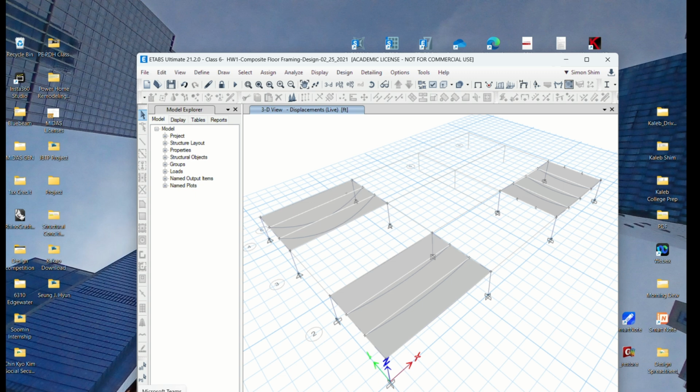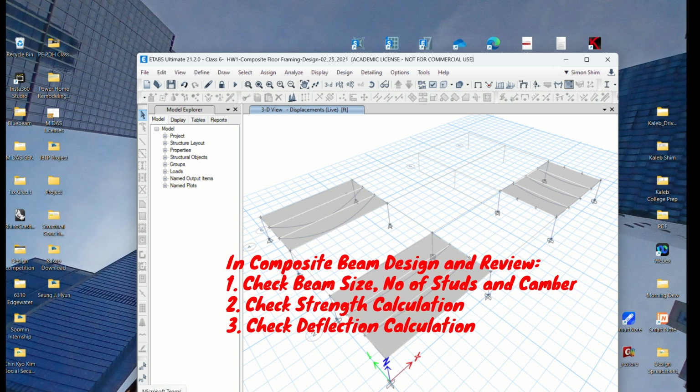In the current modeling, maybe if you're interested, we could mesh the slab and mesh the beam and interconnect them, intentionally connect them, run it, and see how close they are when we define mesh versus composite action beam design. So we can maybe test it. I'll show you how big a difference there still is.